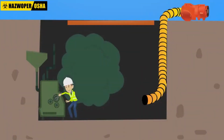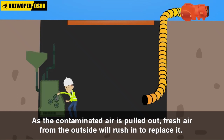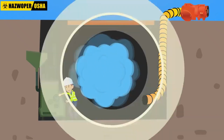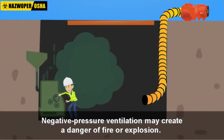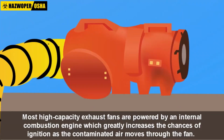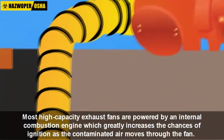Negative pressure ventilation is the opposite of positive pressure ventilation. In this case, air is pulled out of the confined space with the aid of a fan, creating negative pressure. As the contaminated air is pulled out, fresh air from the outside will rush in to replace it. It is important to understand that if the contaminated atmosphere is flammable, using negative pressure ventilation may create a danger of fire or explosion. This is because most high-capacity exhaust fans are powered by an internal combustion engine, which greatly increases the chances of ignition as the contaminated air moves through the fan.